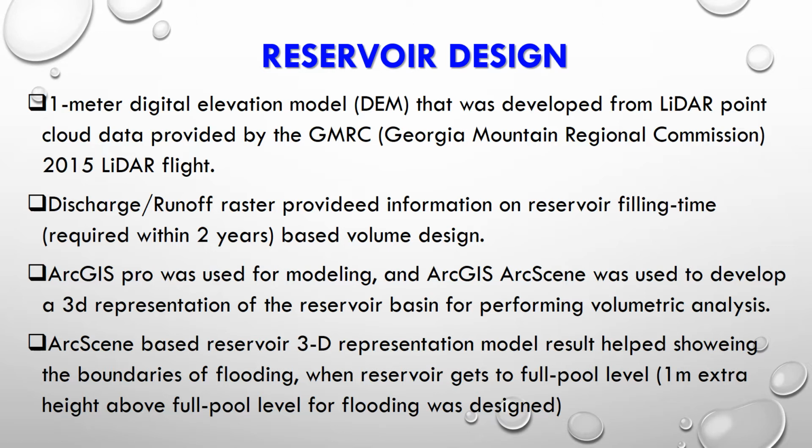One important feature to take note of here: even if we know the amount of runoff coming, we cannot design our reservoir completely based on that, because we need to make sure that high value land and some of the environmentally advantageous land uses, like riparian forest and other land covers, should not be inundated. So we use a 1 meter